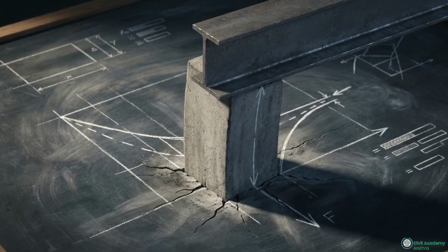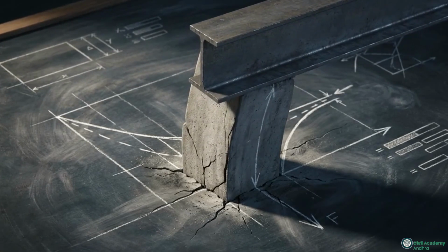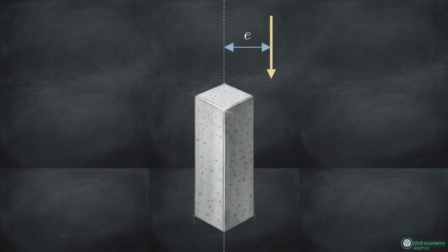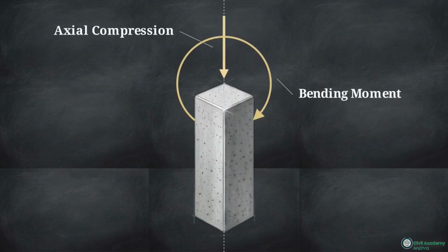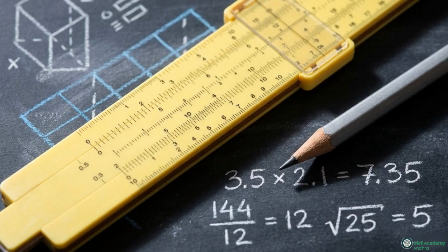We use the couple concept to analyze an eccentric force. This happens when a load is applied off-center, putting unequal stress on a support column. To solve eccentric loads mathematically, engineers artificially resolve the off-center load into two distinct, manageable parts. This animation demonstrates how we model that off-center load. We replace it with a centered downward force for pure compression, combined with a couple to isolate the pure bending rotation. Resolving eccentric loads into a central force and a pure bending couple gives engineers the data they need to predict structural failures, utilizing basic arithmetic instead of relying on complex 3D software simulations.